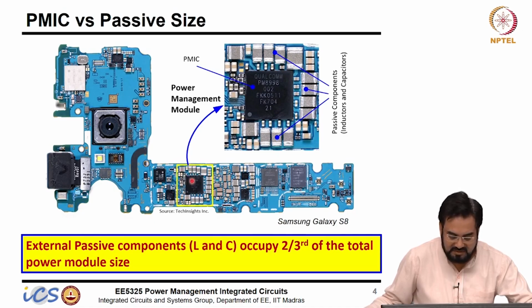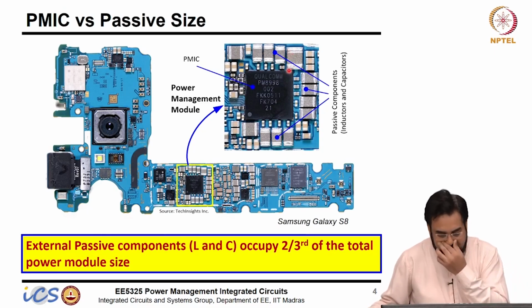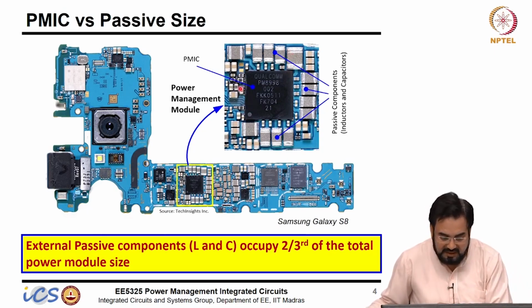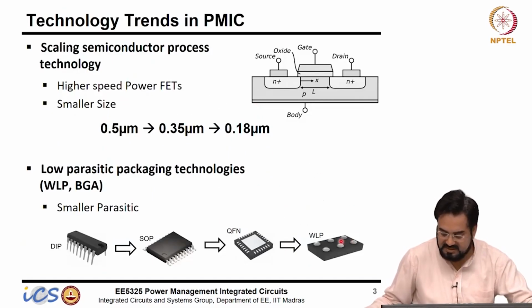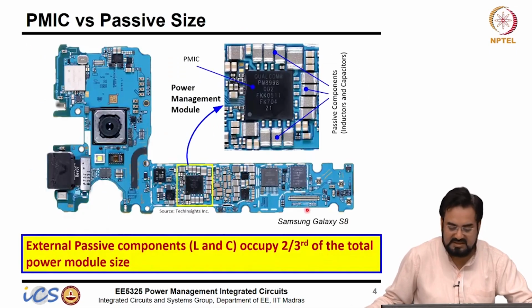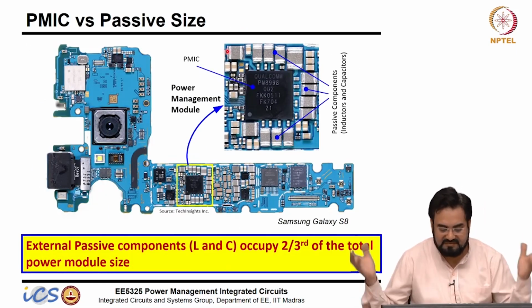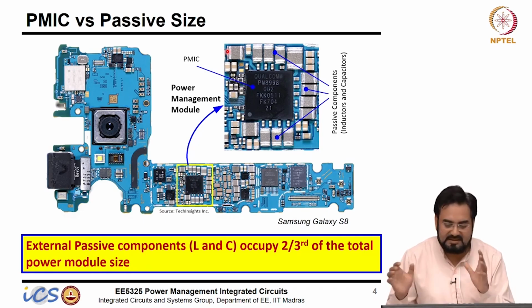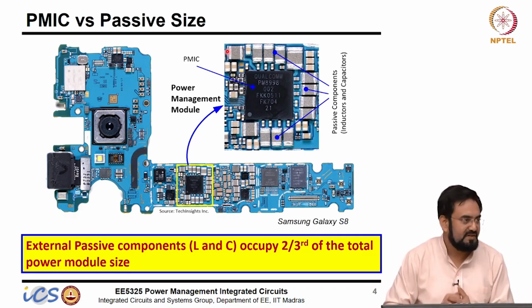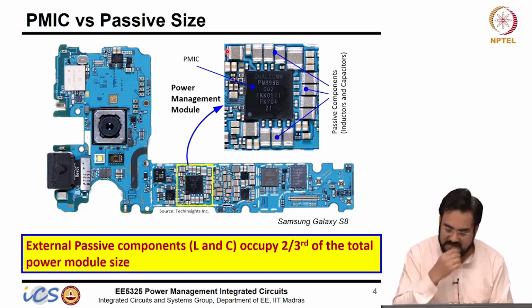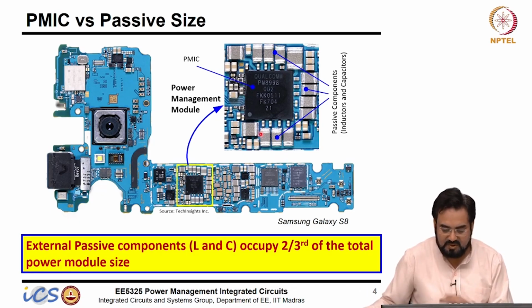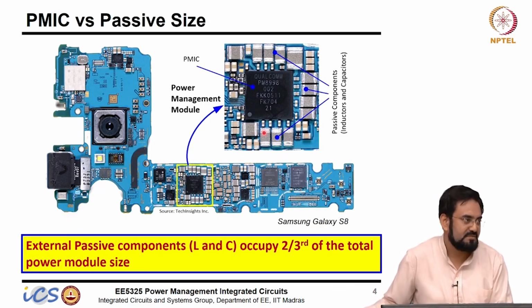So this Samsung phone, this is a Qualcomm PMIC actually, PM8998, and at the bottom, if you flip it upside down, you will see exactly these balls. This is a much bigger PMIC because it has integrated, let's say, 5 to 6 switching converters, then it has more than 25-30 LDOs inside. So you have a lot of power supplies inside, and other than that you have a lot of housekeeping stuff like ADCs, everything for measurement. So it's a more than 200 pins PMIC, you can say.